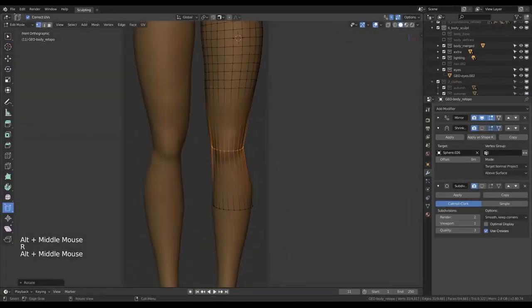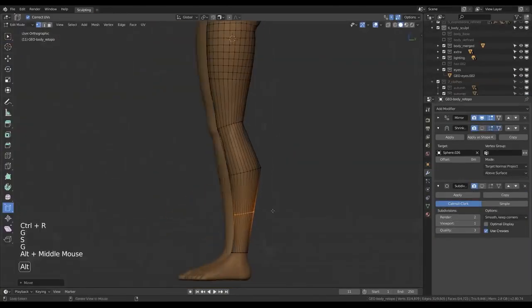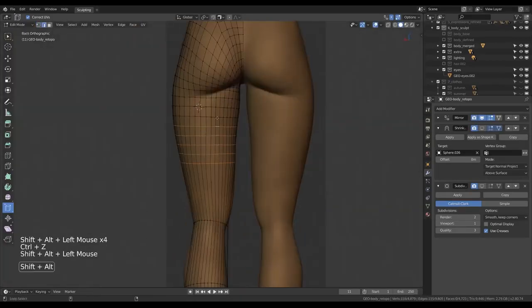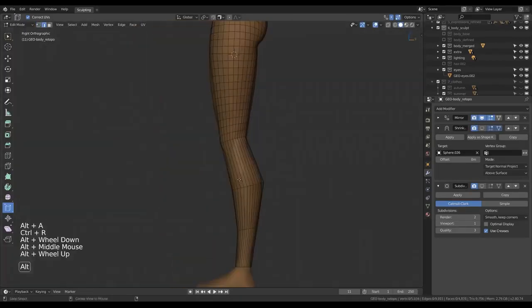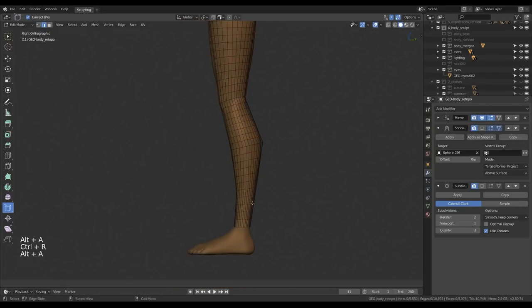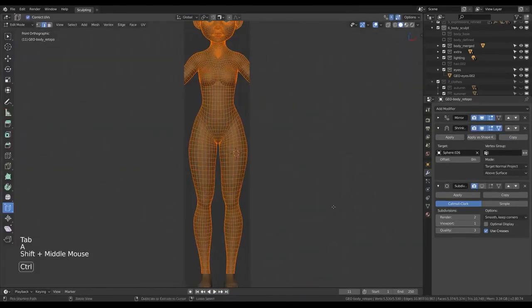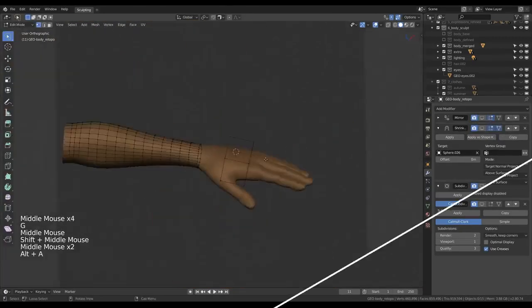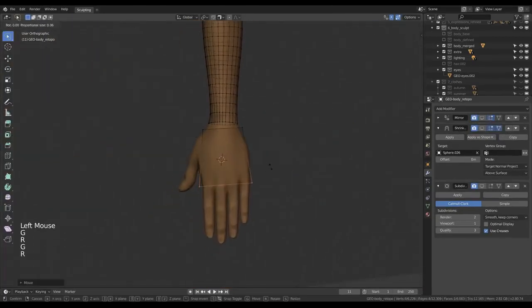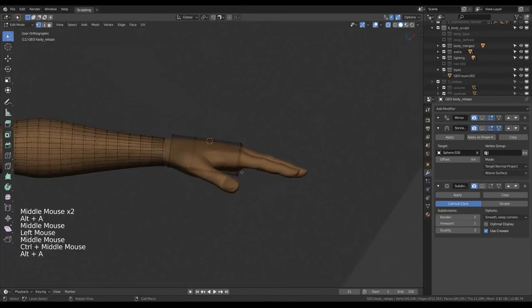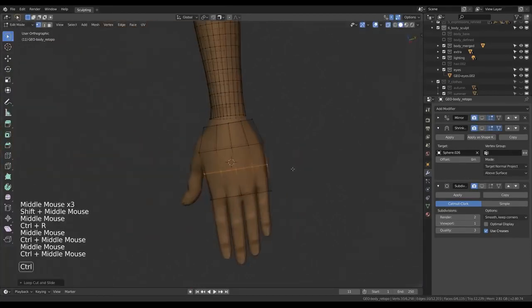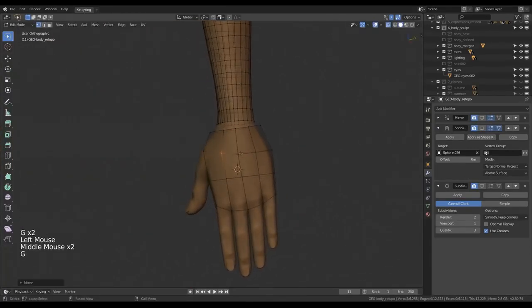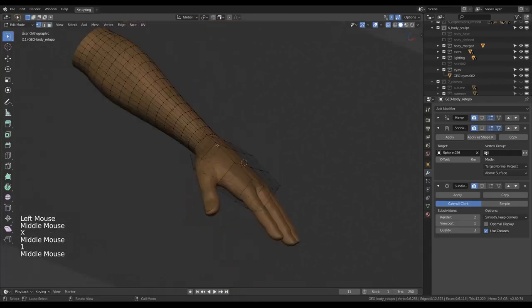Using the subdivision surface modifier will smooth the entire result, so be aware of stretching. That's why you should mostly rely on evenly sized quads all over the place, especially on areas that will deform a lot or are very curved. Creases and hard surfaces are an exception usually, since the former needs more density to stay sharp and the latter doesn't need any extra loops to deform well.